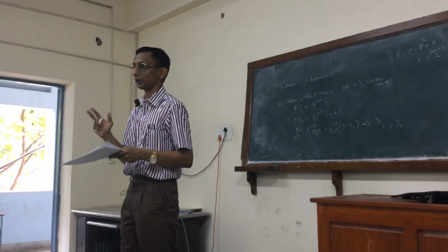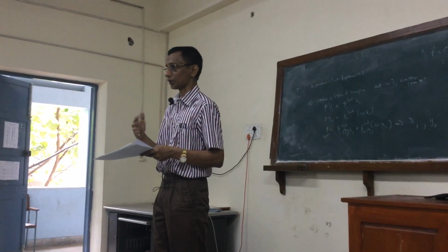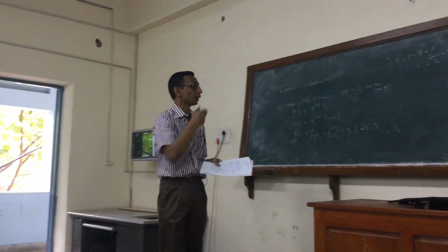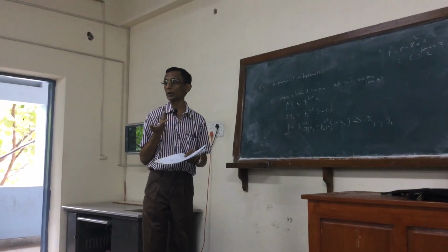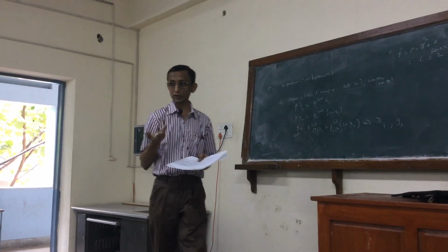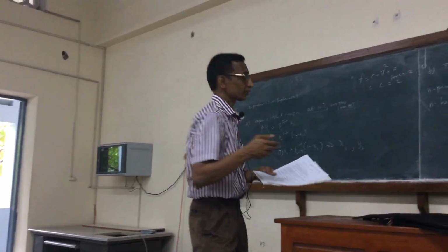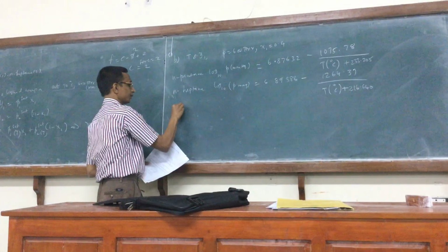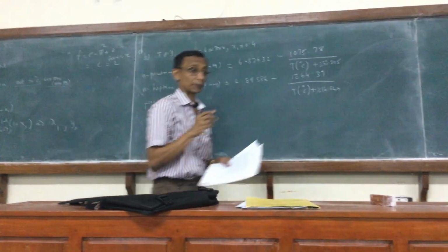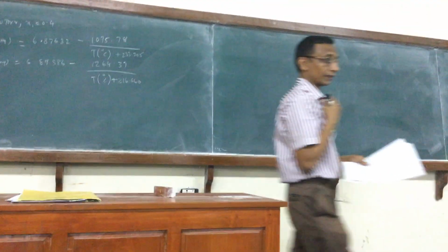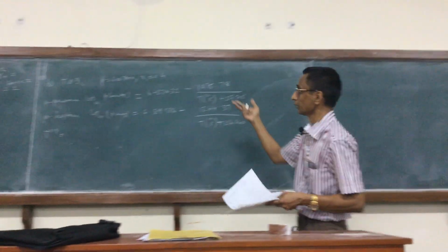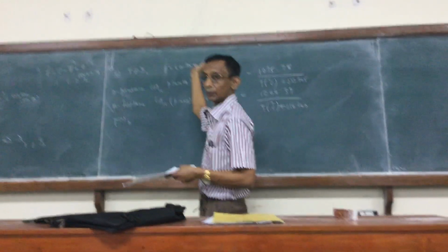We choose the algorithm where the ratios of the saturation pressures come into play. We also look at the other algorithm which we discussed right at the beginning. So what is the first step in calculating bubble temperature? You have to choose a temperature, right? So T naught, a good choice would be, and in an exam, for instance, I could say choose it so that it is the weighted average of the boiling points.